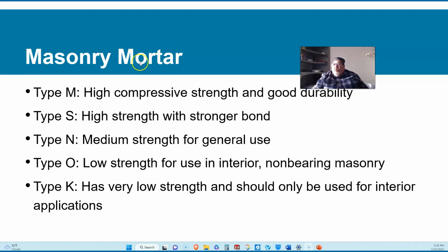So when you mix mortar, the cost of your mortar can vary by the type of mortar you're trying to create. If you want something that's high strength, you're going to be using more of a certain material, more aggregate, more cement, or you want to do something that's more for looks and not necessarily meant to have high strength, because you're going to use it more for aesthetics. So maybe a type K would be more acceptable.